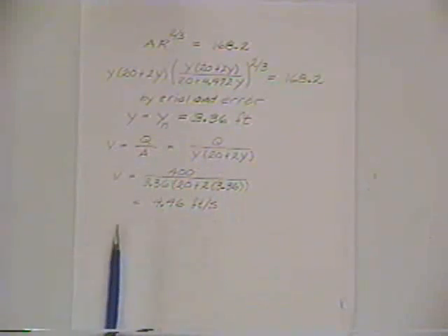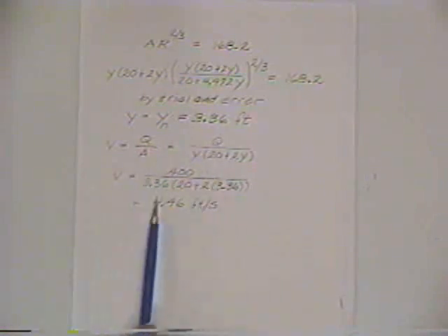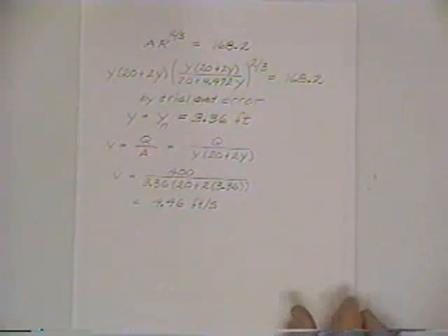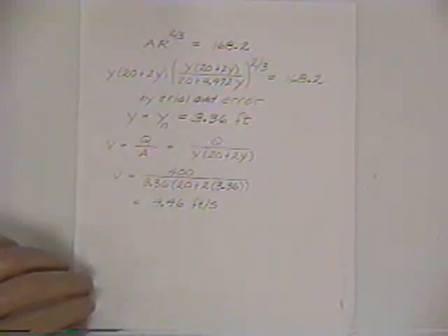And then from that, we've got the depth. If we wanted the velocity, we divide the discharge by the area to get the velocity. And so that's basically using the Manning's equation. The geometry is a little more complicated in a trapezoidal channel. A rectangular channel simplifies the geometry. And so the problem can be given for a given geometry, compute the flow rate, or vice versa, for a given flow rate, compute the geometry.